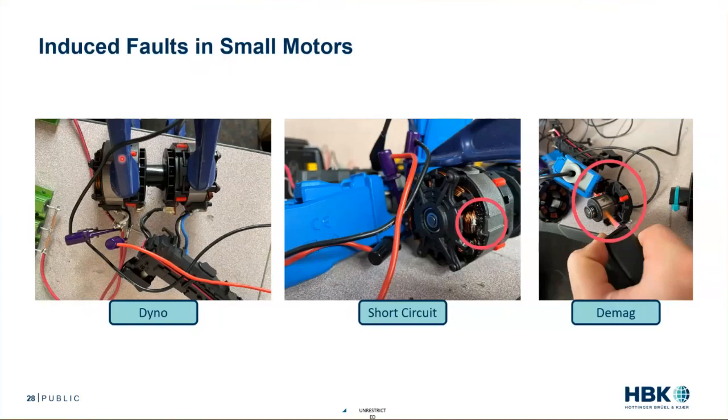But here's my little dyno. I have 2 drill motors, and I just hooked one motor up to a resistive load, so it's kind of like a constant torque dyno. I have the other motor hooked up to my inverter, which is just the trigger of the drill hooked to a battery, and I'm making voltage and current measurements on the 3 phases.